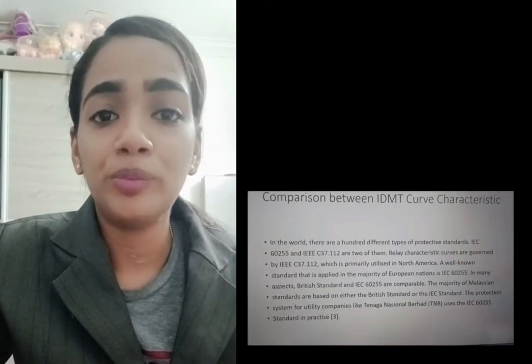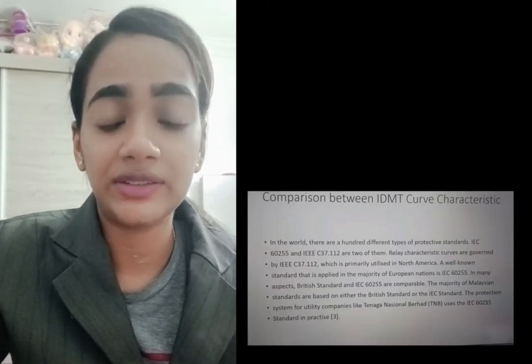The majority of national utility companies adhere to the IEC 60255 standard. As illustrated in figure 4, the fault is present in a number of locations, including the grid, transformers 2, 3, and load 1. Each of these locations has a single phase to ground, double phase to ground, or 3 phase to ground fault.